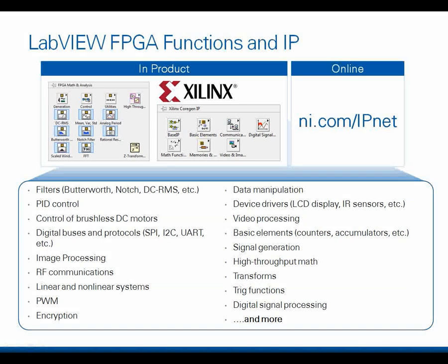FPGAs are great options for implementing high performance IP, whether it's high-speed control or a custom digital protocol. However, you don't always have to build your IP from the ground up. A lot of times you can look to see what's available and incorporate existing IP into your design. With the product, LabVIEW FPGA includes math and analysis libraries such as matrix algebra and PID control. It also includes access to a wide array of Xilinx CORE Generator IP.